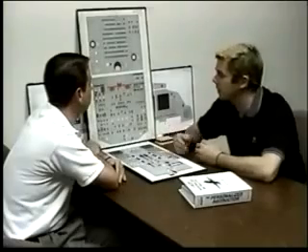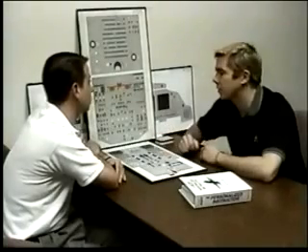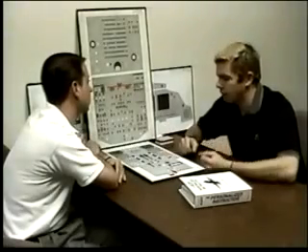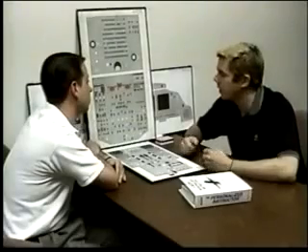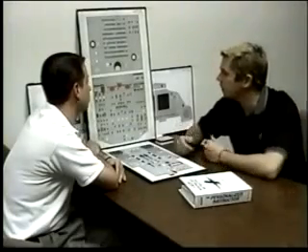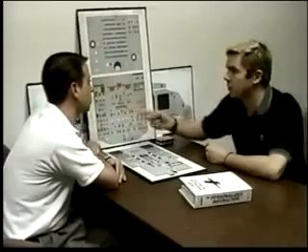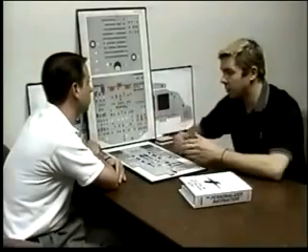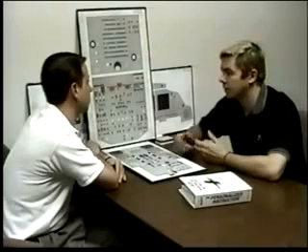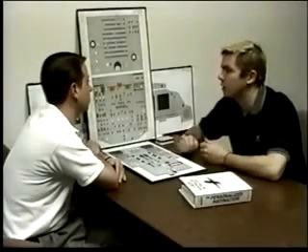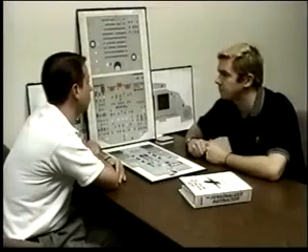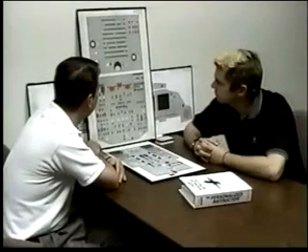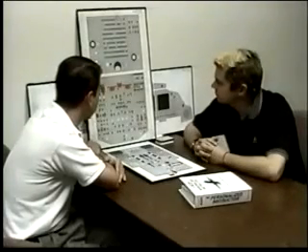But let's say we get to my destination and I still have fuel in the center tanks. I'll move the flap handle out of up, and the slats are going to come out. This will cause the center tank pumps to stop running. When I land, they'll still be stopped until I bring the flaps up. The slats will retract, and then the center tank pumps will again be able to run. In that scenario, let's assume that you burn the center tank fuel.